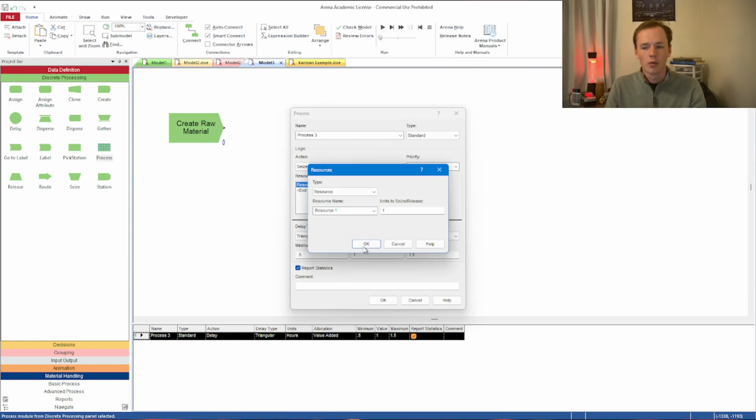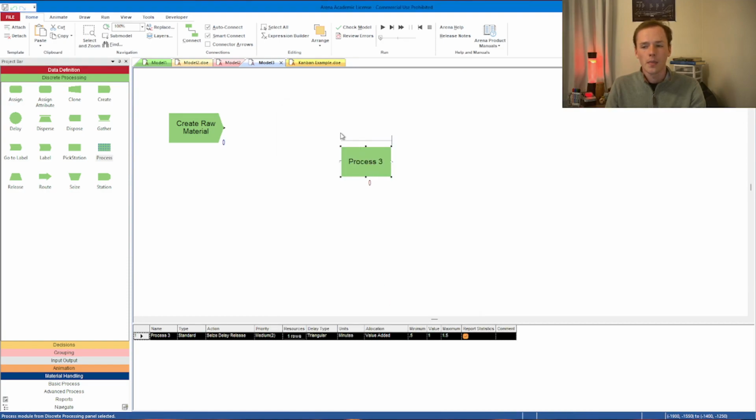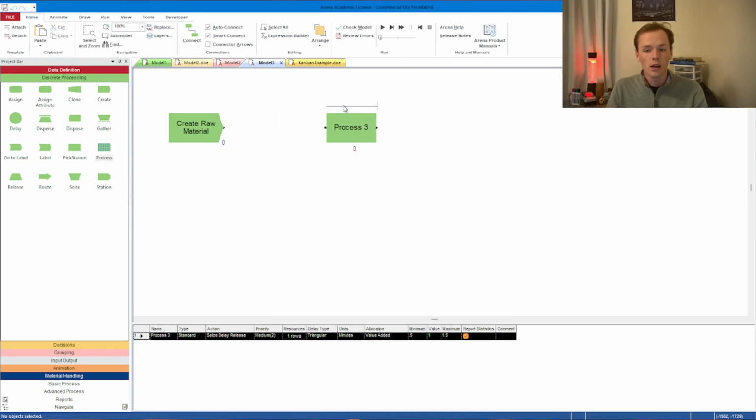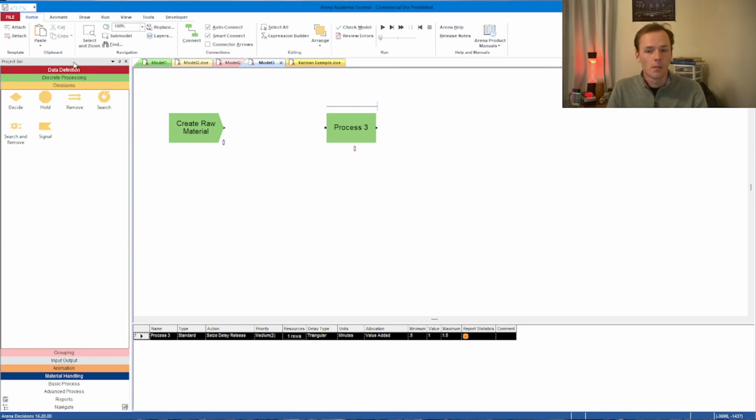On average, add resource 1 if something is required. This is a process module, but we want to make sure that you're only releasing things from the queue at a controlled rate. You don't want to overwhelm this queue. You don't want it to get too big. Now you could do some stuff with the queue specifically and tell it how large you wanted it, but the other thing you could do is have some Kanban cards and just do a one card Kanban system.